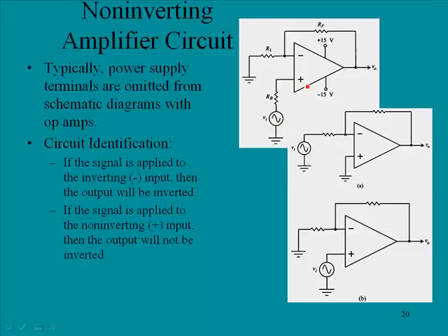Remember that we have infinite impedance here, and this particular component is only there as a balancing component for this one. Remember that we had that current, though it was very small, that came out of the bases of the differential amp, and it flowed out of the inputs. And remember that current flowing across R1 will create a tiny voltage. This component RB is only placed there to offset whatever voltage is developed on R1 due to those currents. But for purposes of calculation, this value can actually be ignored.